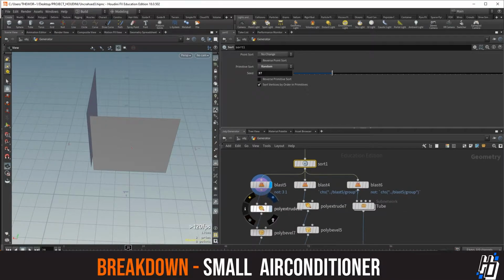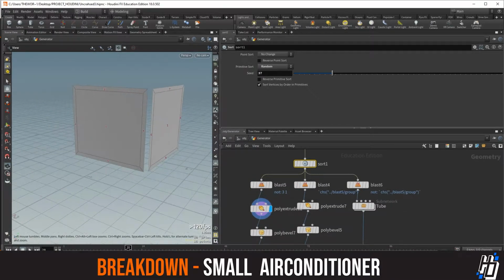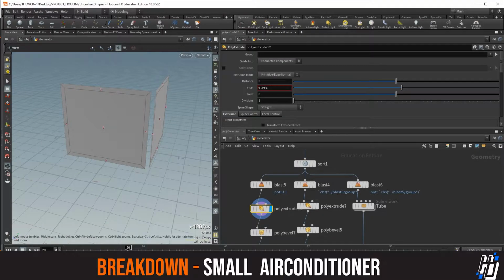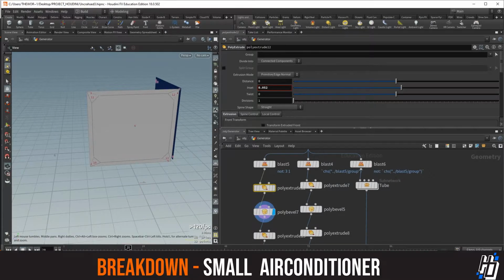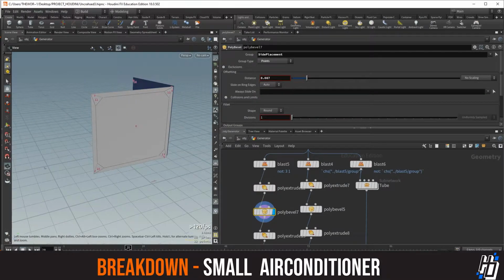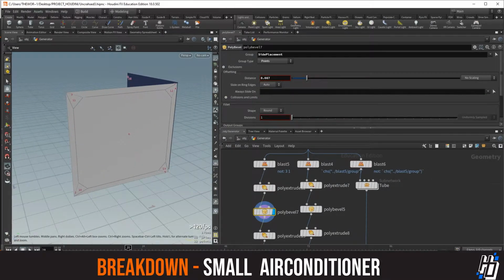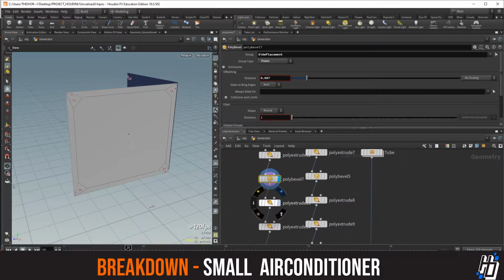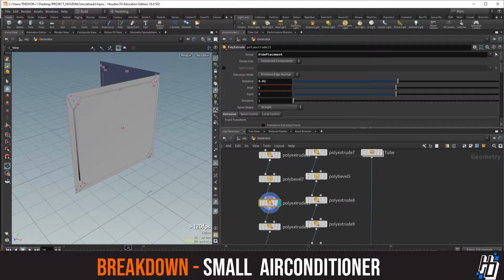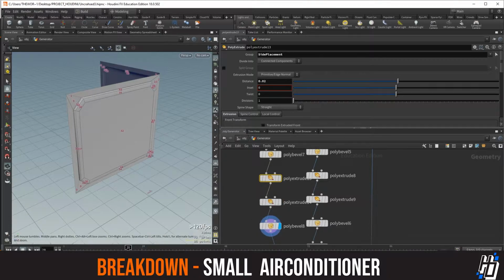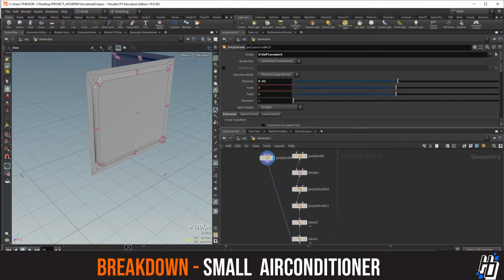So with the 3 and 1 faces, I made a poly extrude, just an insert. After the insert, I've booleaned it, booleaned the points, get some different looking panels, and then I did an extrude. After that, an insert, and that's it.